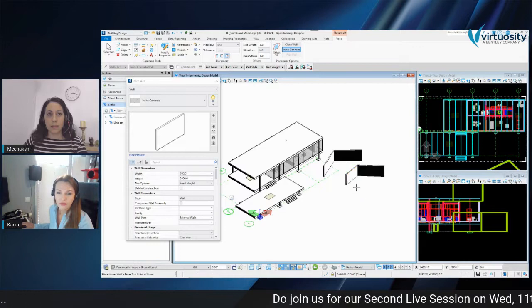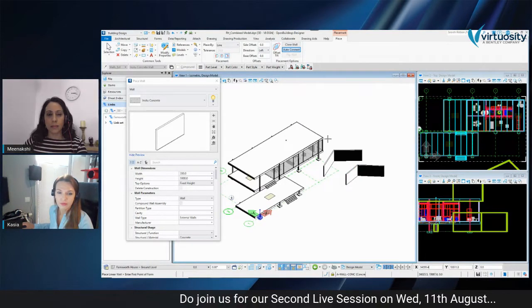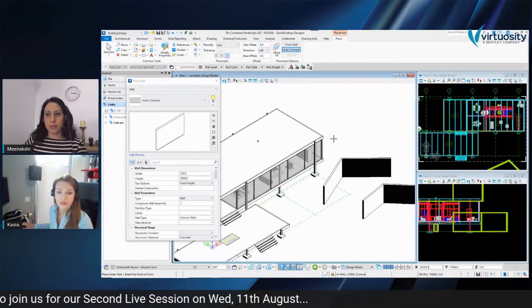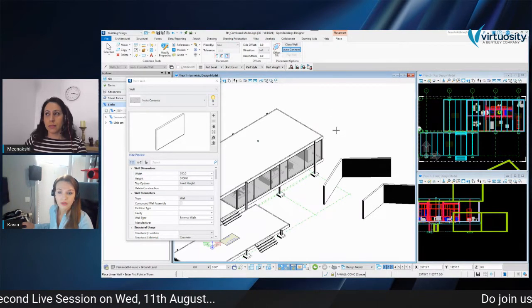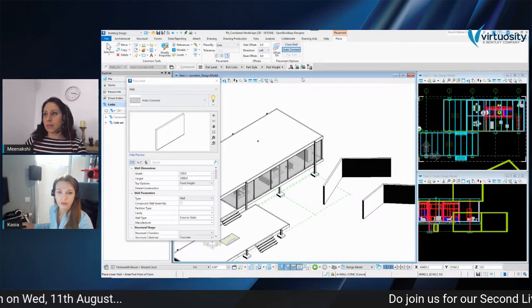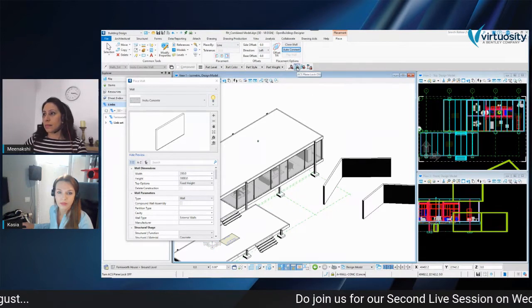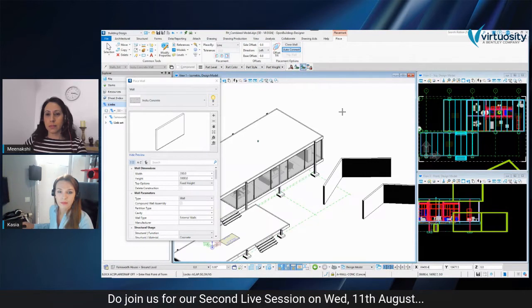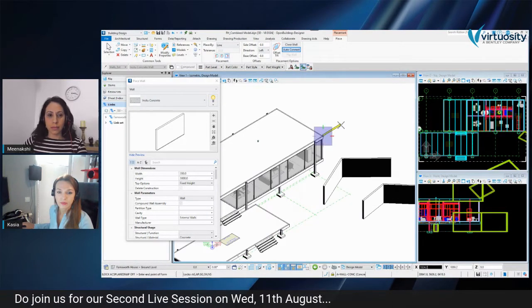Of course, there are situations when we maybe want to snap one of the elements to another element that exists in a project and doesn't correspond with any level, then we can use the locks here. It's the ACS plane lock and the ACS plane snap lock, and then I can snap to one of the elements.